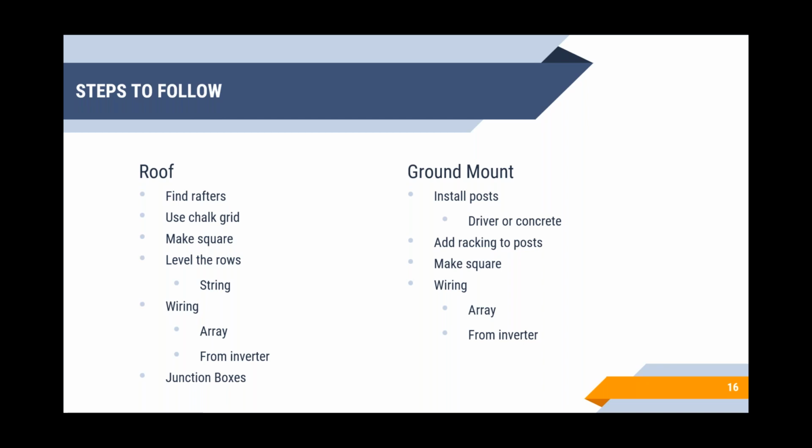Then on ground mounts, we install the posts. That can be done with a post driver, or you can actually do it in concrete, and you could just auger out the hole, come back, fill it with concrete. I've heard of some people even adding in some rebar as well. And then you start to add your racking to your posts, and we actually have a live working array here at Enertech that we can take a look at on the 8th to show you in steps. And then we'll also be having one locally as well that we can take a look at that will be in